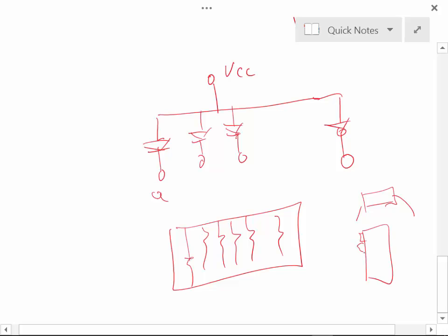You've got the pins here. It looks just like a normal IC, only instead of having electronics in there, it's just got resistors. It's basically a 7 resistor pack designed to be used with a 7-segment decoder driver and a 7-segment display. And that's how you run your 7-segment displays.